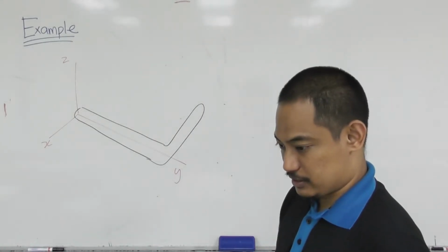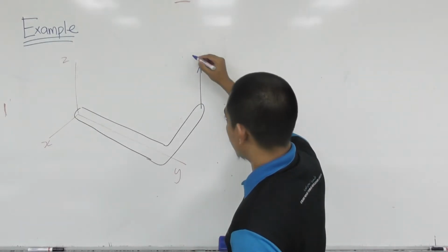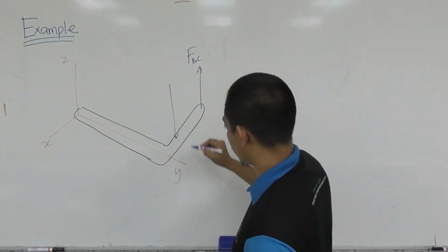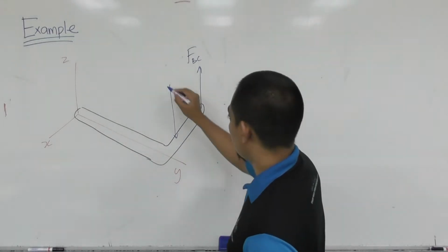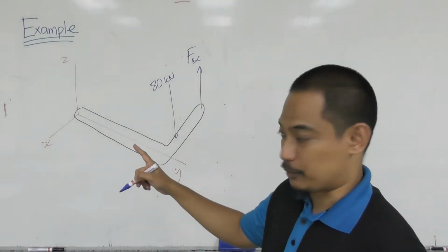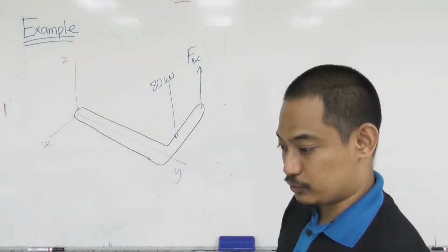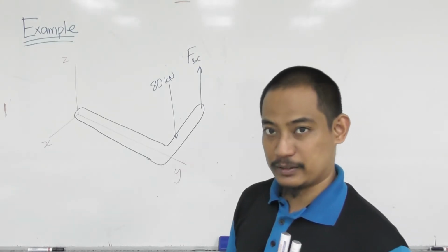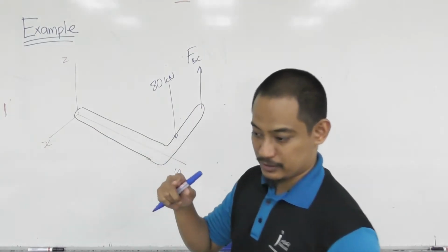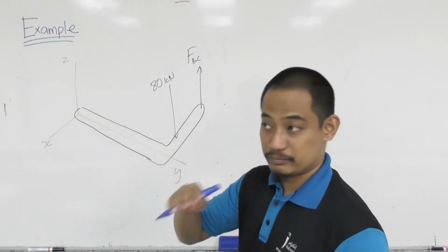And we have the forces from the cable. So we have a force upward from the cable. Let's name it F, BC. We have a force downwards, which is 80 kilonewton there. And also we have the support reaction at point A. As we have mentioned, we have forces in all three components because it's a thrust bearing. It doesn't allow movement, including in the x-axis.